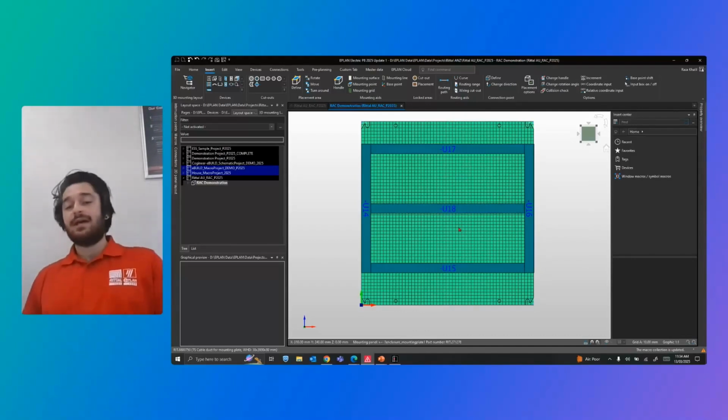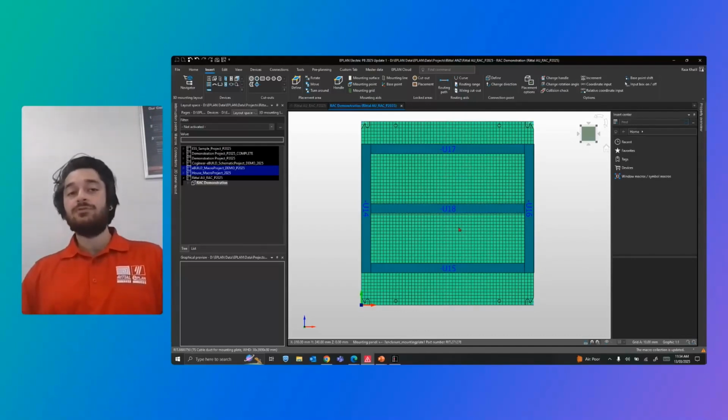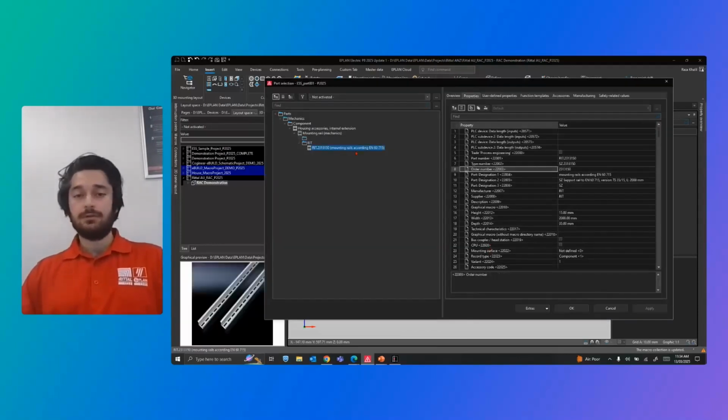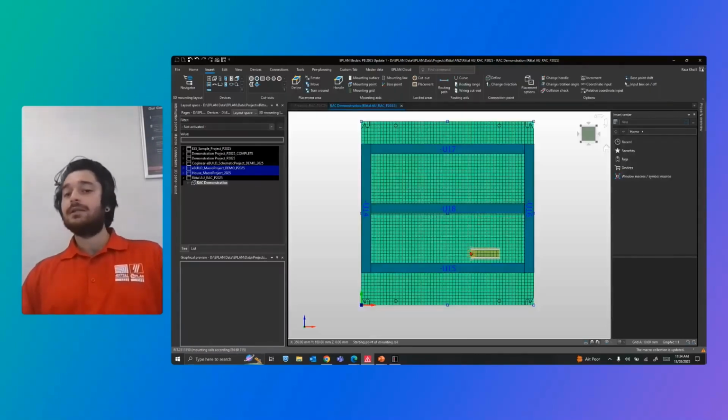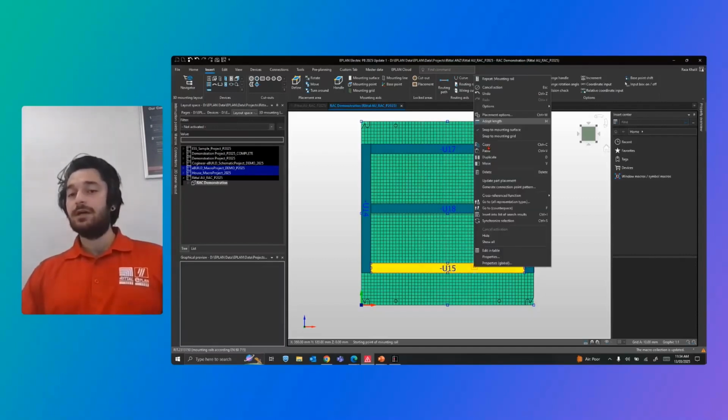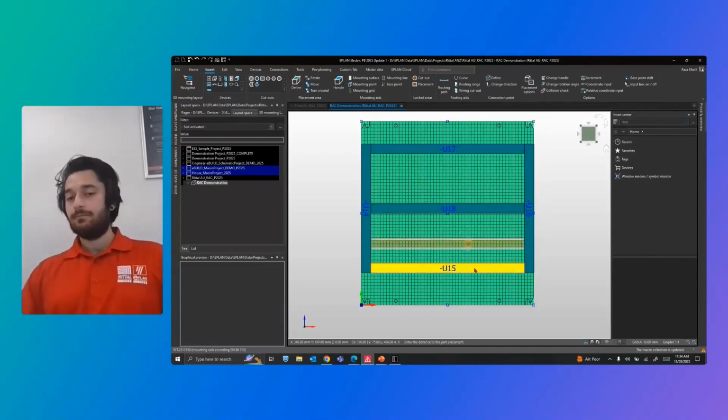These same functionalities can be used for your mounting rails as well. So I'll show that now. I have just one mounting rail. Let's use that. I know that the length is U15. Right click on U15, adopt length. Okay, I know that it's meant to be placed dead center between U18 and 15. Place centered, done.